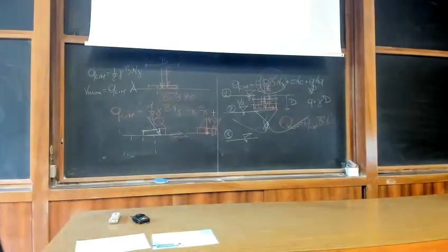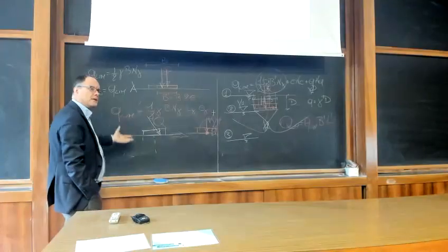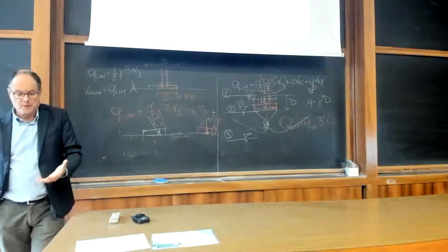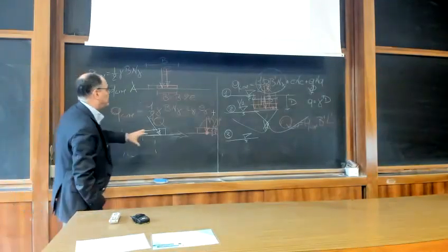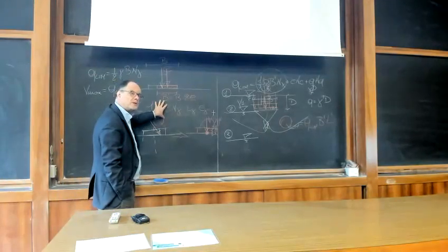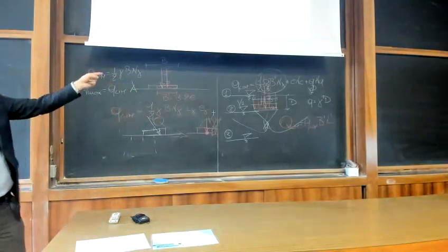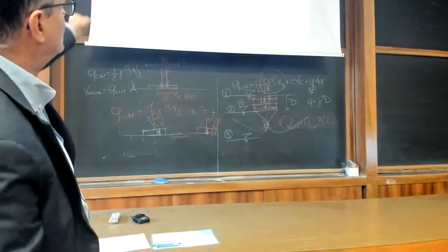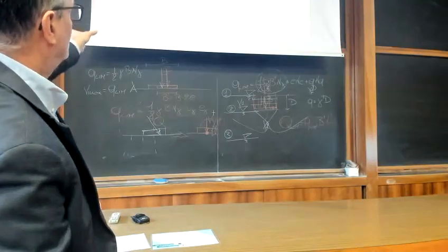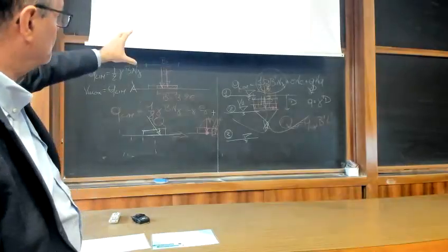And finally, if you want to use the partial safety factor approach, which is what we typically do with the new Eurocode, for example, you apply partial safety factors to the soil parameters, and you amplify the loads. If you reduce your soil parameters, you have a strength reduction. From the dashed line, you reduce your failure envelope to the black line in the bottom graph.